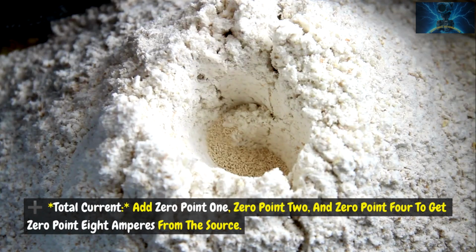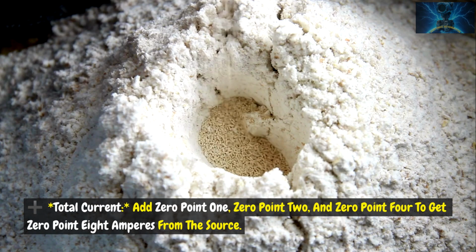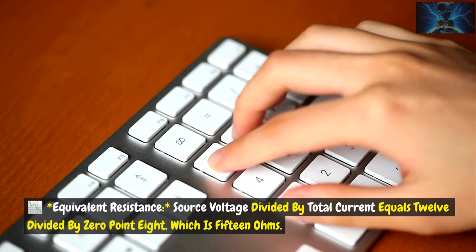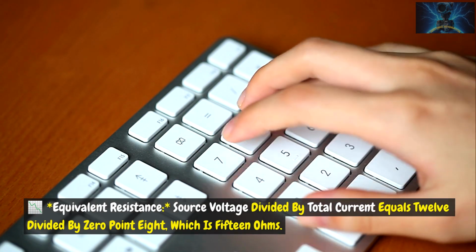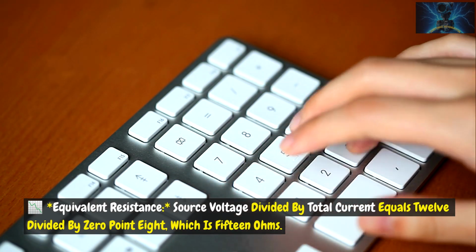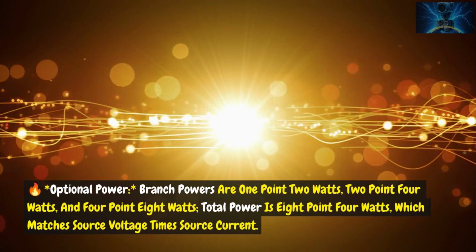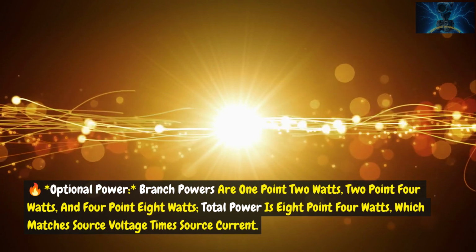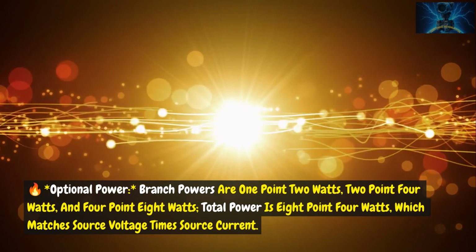Total current. Add 0.1, 0.2, and 0.4 to get 0.8 amperes from the source. Equivalent resistance. Source voltage divided by total current equals 12 divided by 0.8, which is 15 ohms. Optional power. Branch powers are 1.2 watts, 2.4 watts, and 4.8 watts. Total power is 8.4 watts, which matches source voltage times source current.